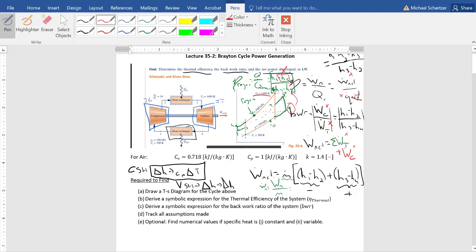And then when you know H9, you come back into the regenerator, and then you say, okay, because I knew H9, then I knew H5, and then on the other side of the regenerator, you'll try to find the real exhaust temperature. Because all this real heat that went into the cold side of the regenerator had to come out of the hot side of the regenerator. So then you can find the exhaust temperature, right?